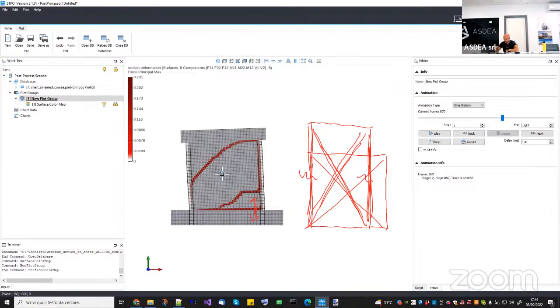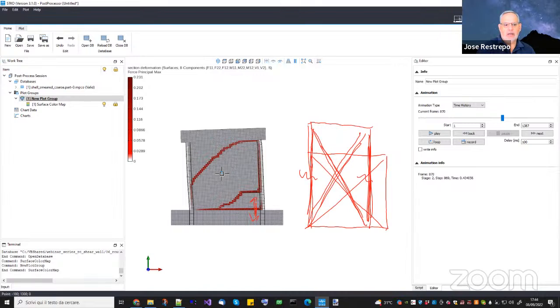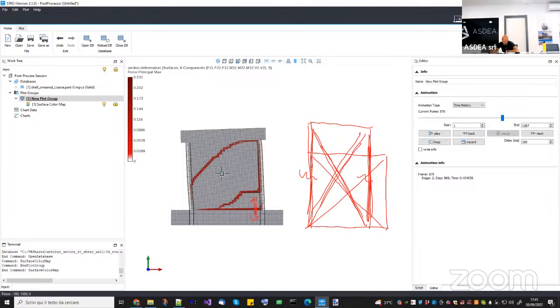Okay. So yeah, I think if you have a large tensile strain, you will not affect the compressive stress-strain relationship unless you have high shear stresses in that region as well. So what we have done here is that we have totally uncoupled it. The tension has no effect whatever on the compressive stress-strain relationship. In fact, exactly. So that's why I think probably you will be a little bit on the upper bound.